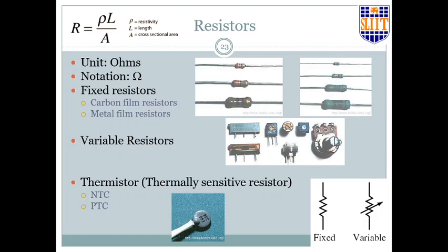So by doing all this, you can create a long thin wire. And ultimately, they put two metal caps to which the lead wires are connected. That is what you can see on either side as two plugs. Right? Has anyone broken a resistor and seen inside?